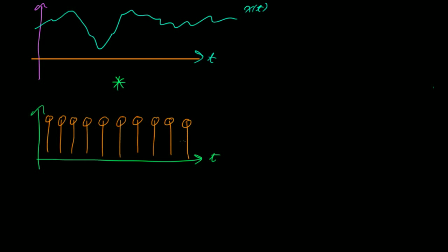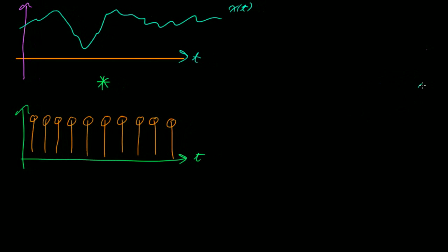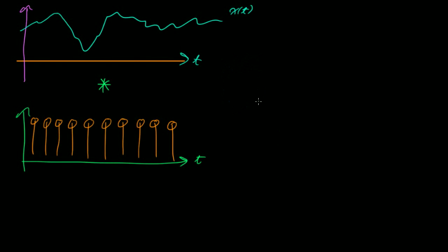But the whole point is that I'm multiplying here. So now I want to look at it from a frequency perspective. So let's just assume I'm not even going to bother trying to figure out what that whole Fourier transform looks like. I'm just going to approximate it. I'm going to say that it's band limited, which means that it has to lie between two different frequencies. And let's just say, for our intents and purposes, that it looks maybe like this. Right, between negative B and positive B frequencies.